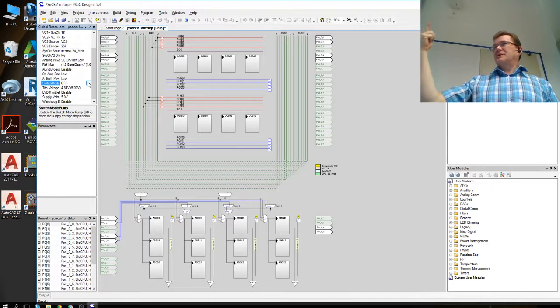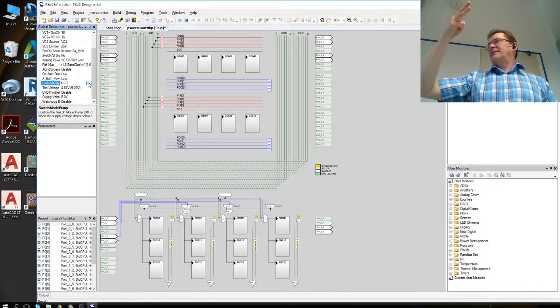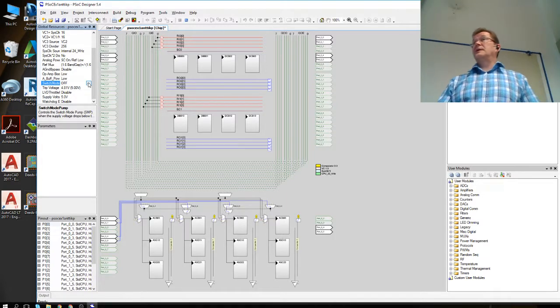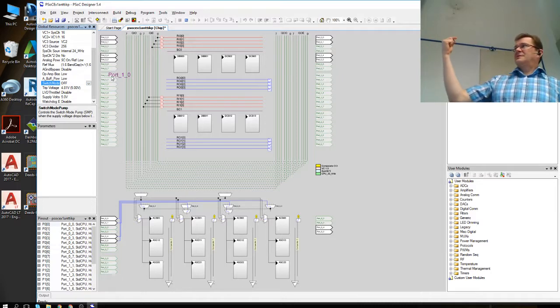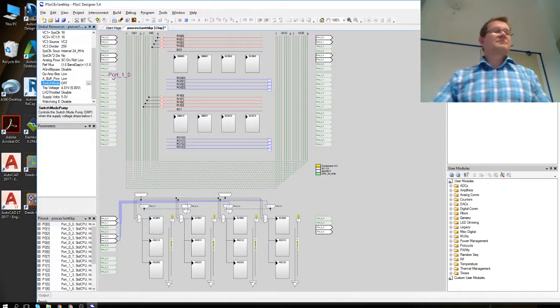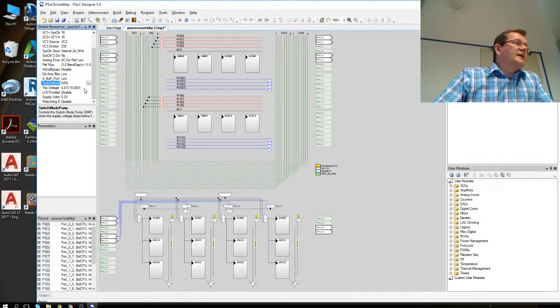Capacitor as a charge bank, then you need the inductor, and then usually the diode also, but the switch. So yes, capacitor for charge bank, inductor to make the current going, and then switch to switch it, and then the diode to prevent losing of the power from the capacitor. Okay.